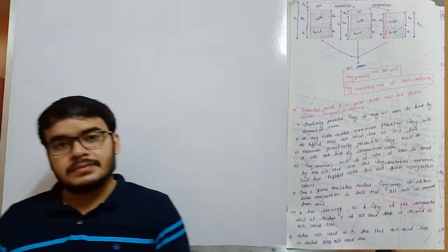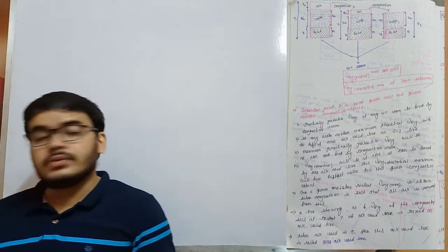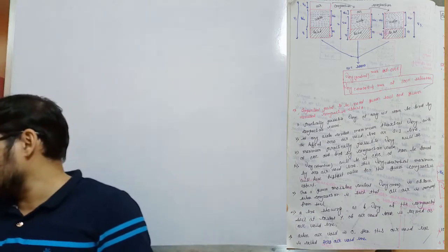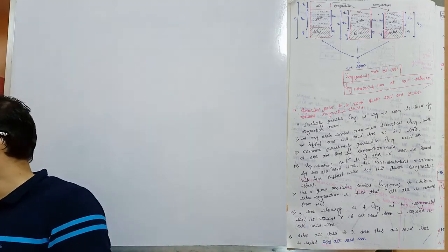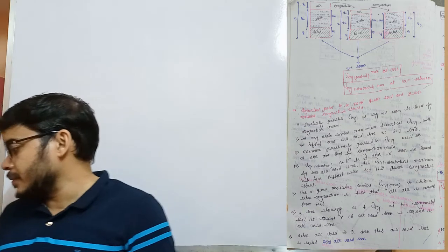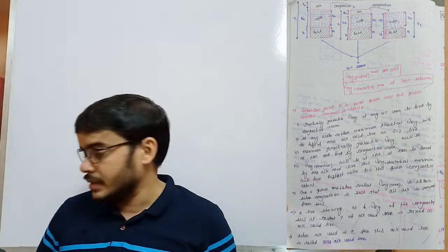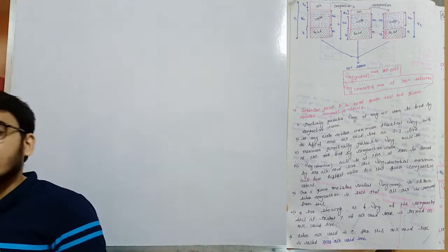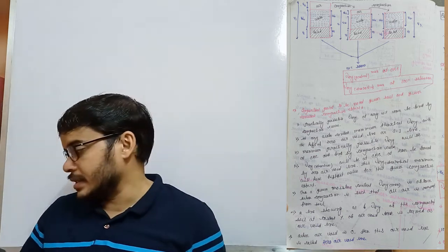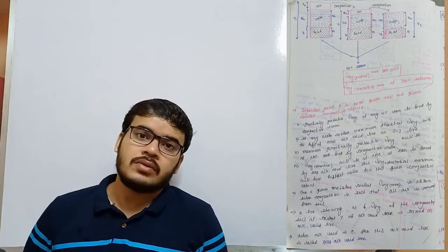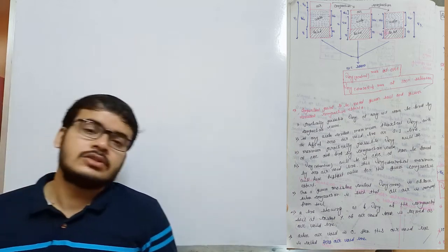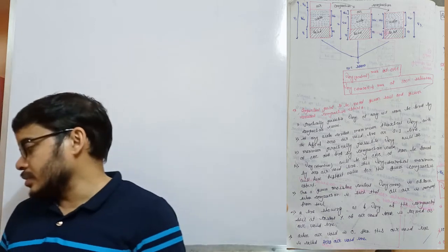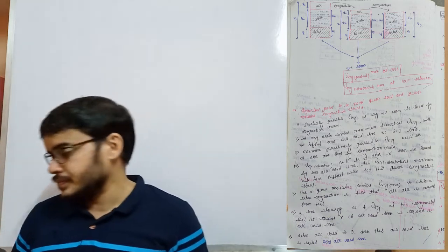So now check this diagram here. Three stages are given. In the first case, solid, water and air. Then after compaction, some amount of air has been removed, and after that, compaction is performed again, and then all air has been removed. That means at this stage, the soil is at 100% saturation. And after this, when we apply load, water will start to be removed, and that process is called consolidation. So these are the stages of compaction.